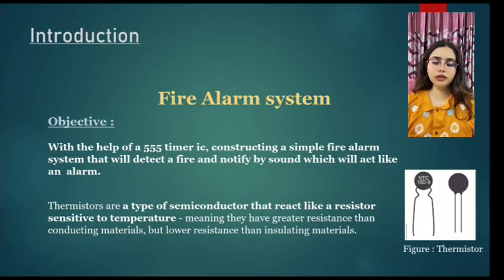Now I will discuss fire alarm systems. With the help of a 555 timer IC, we can construct a simple fire alarm system that will detect a fire and notify by sound, which will act like an alarm. Thermistors are a type of semiconductor that react like a resistor sensitive to temperature, meaning they have greater resistance than conducting materials but lower resistance than insulation.